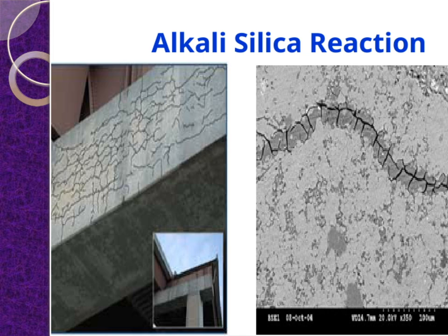The key points to remember are that ASR can significantly compromise the durability and structural integrity of concrete structures. To prevent or mitigate ASR, proper selection of non-reactive aggregates, controlling the alkali content in the cement, and using supplementary cementitious materials are effective strategies. Understanding ASR ties into the overall theme of durability and long-term performance, emphasizing the importance of proactive measures in concrete design and maintenance.